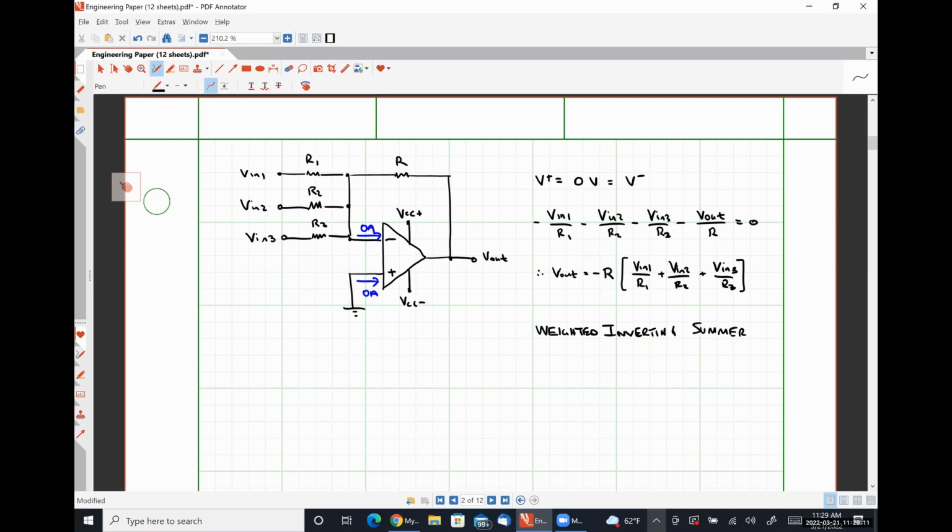Let's say a load cell converts 1 ton of weight to an output voltage of 1 volt. Each of these input signals would be the output of a load cell measuring the weight at each axle, and the circuit simply adds them all together and tells you the total weight of the vehicle.